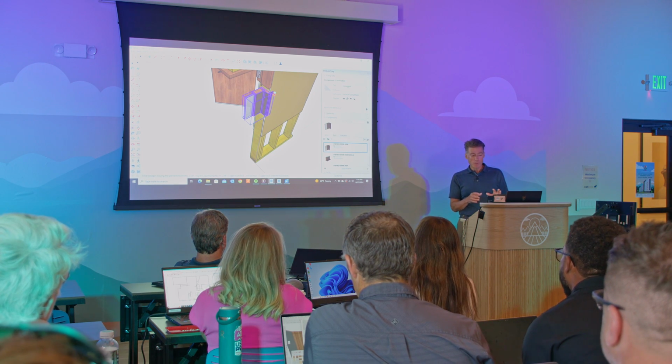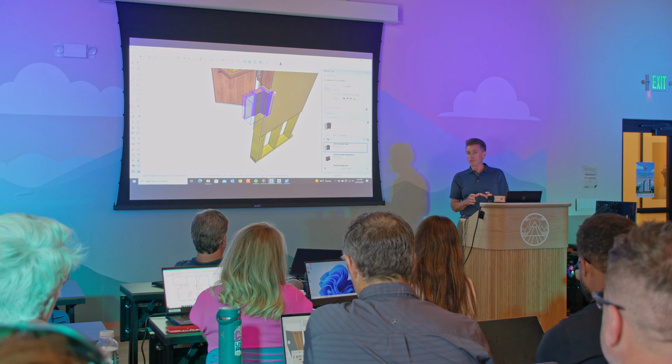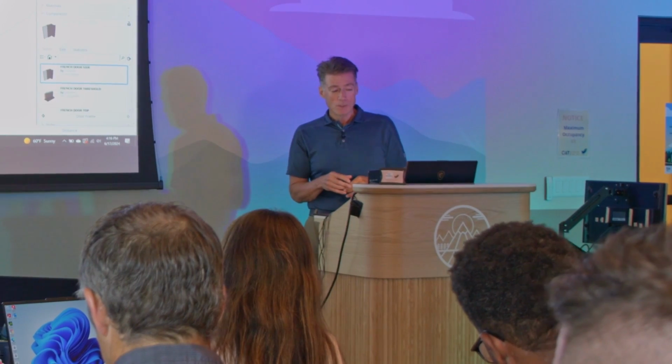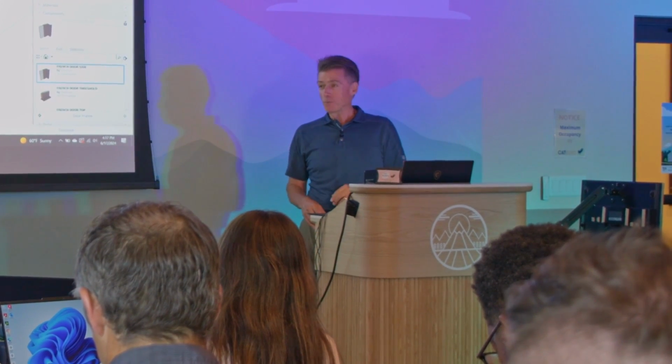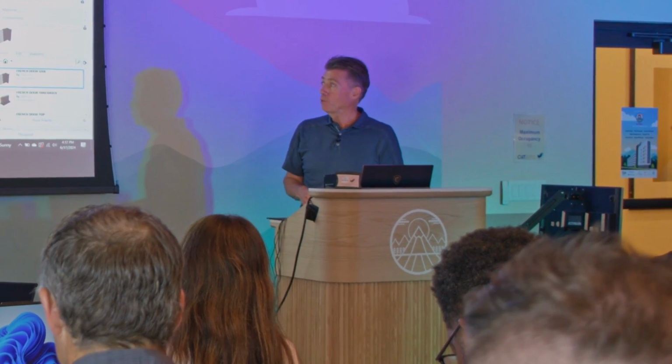And then I'll put a model on it of, for instance, the flashing tape that goes down, and tell them which order it goes in. On a door, you do the sides, the jambs first, then the head last. On a window, you do the sill first, then the jambs, then the head. So it tells them how to properly flash a window and a door.